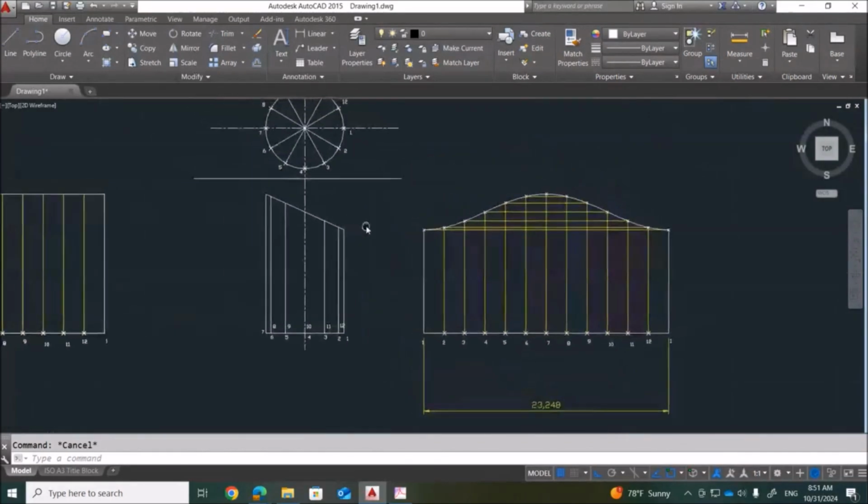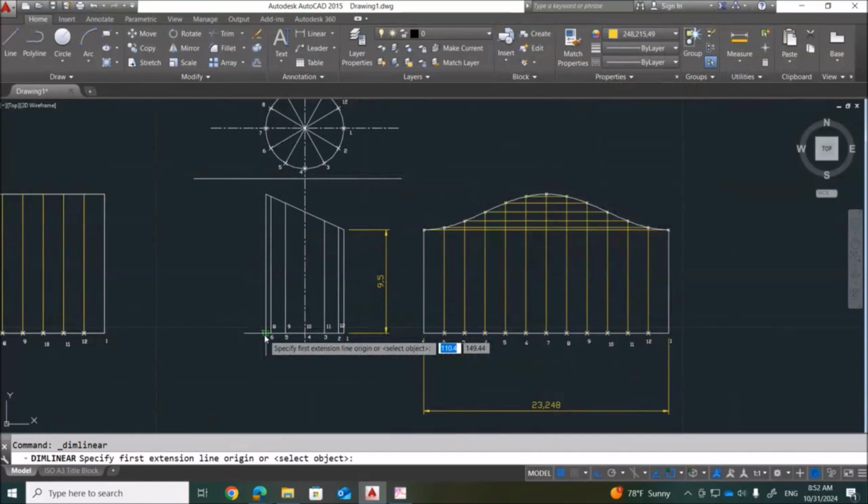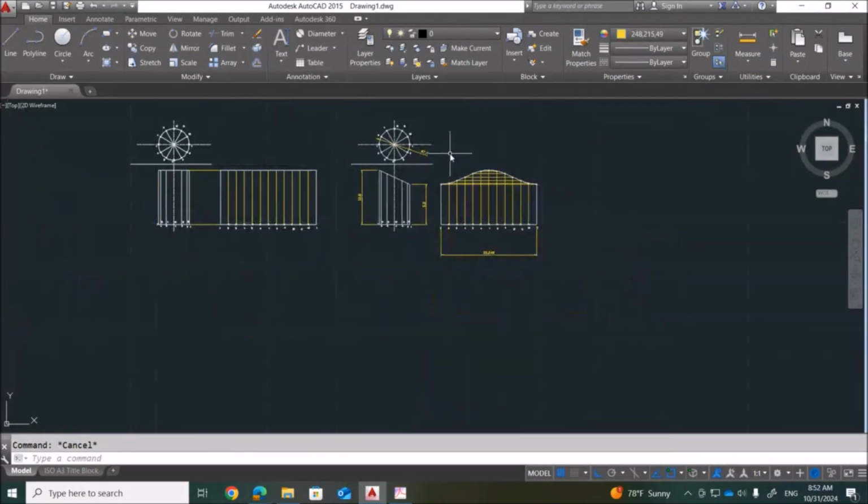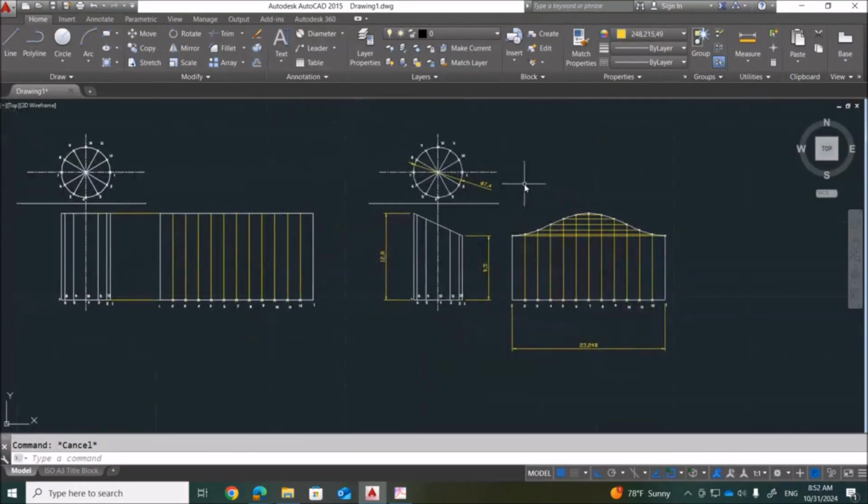This is a calculation. And one more thing I need to mention is what is given to me here, this height. Select it, make it yellow, escape, and I will give this height as 12.8, and the diameter, not radius, diameter is 7.4. This dimension should be there. So this is the development of the surface for the cylinder.